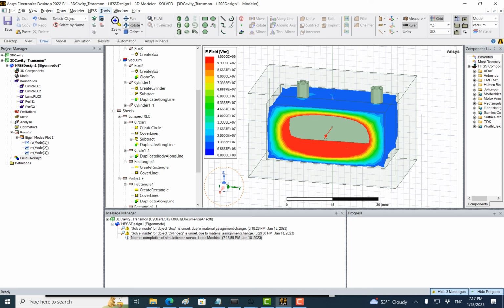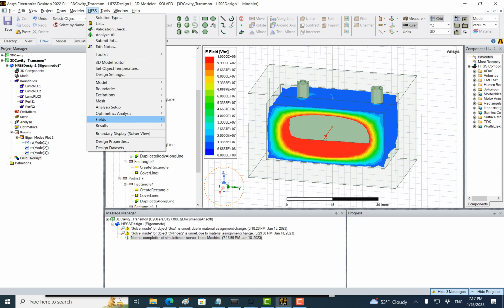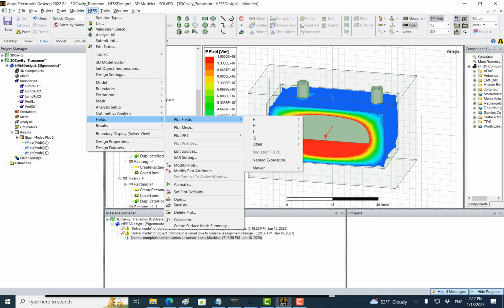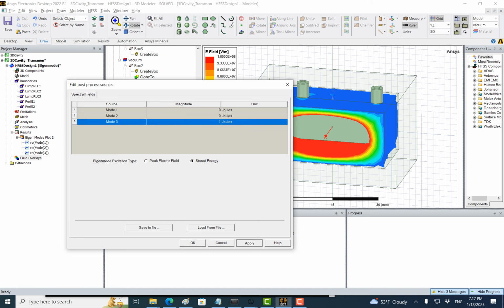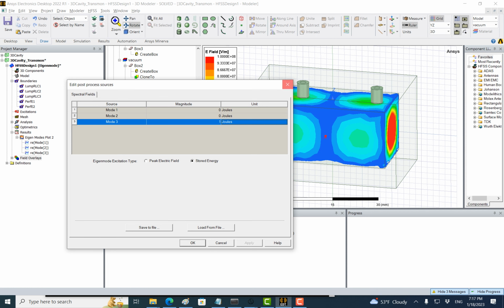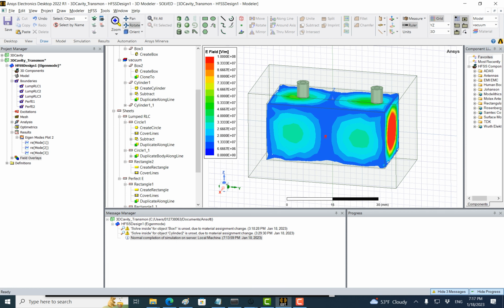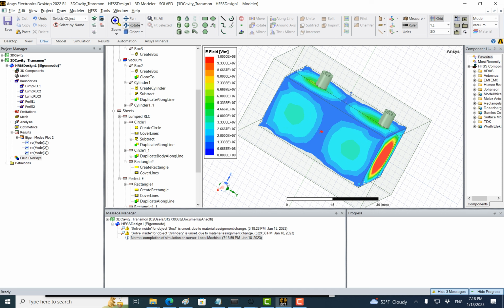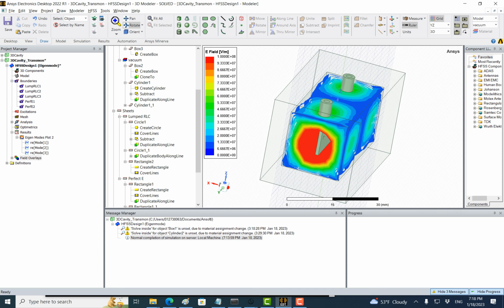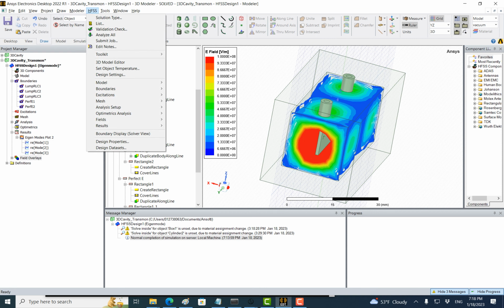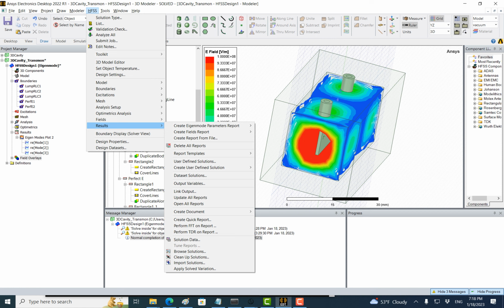Okay, will it be the third mode? I'm going to edit source. Because I did not design this well, I did it arbitrarily, so this is not a good qubit resonator. Okay, so unfortunately, this is also a cavity mode, right? Do you see that? This is the third mode of this cavity, right? So I think the reason was because I have an inductance too small compared to what we usually have, right?